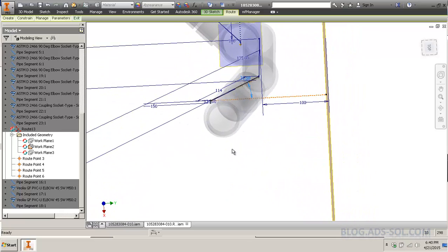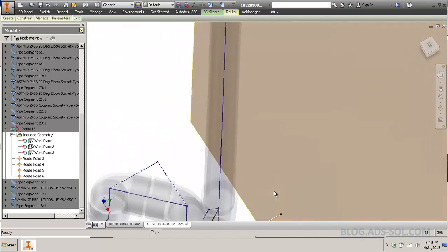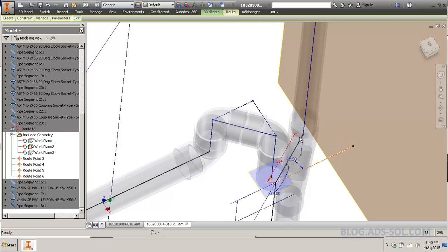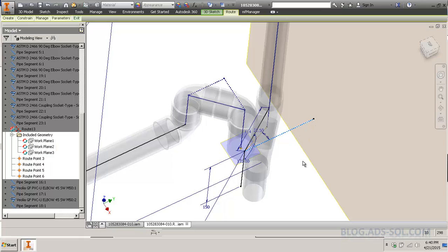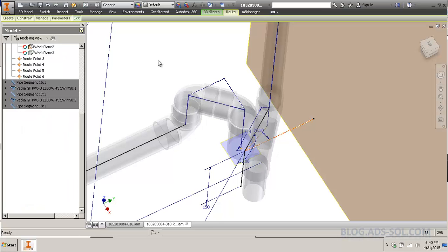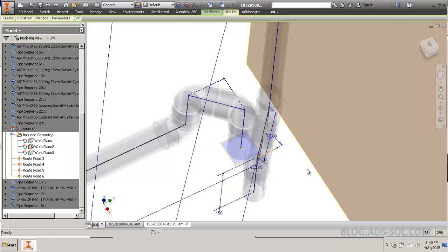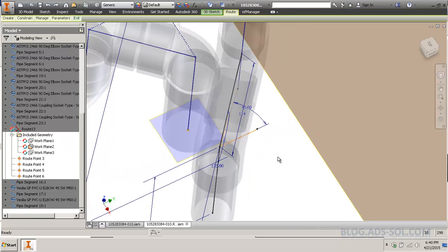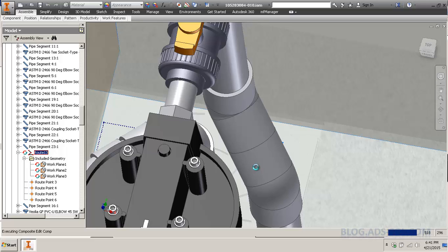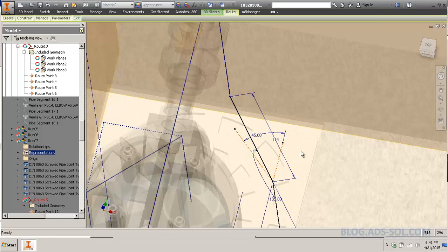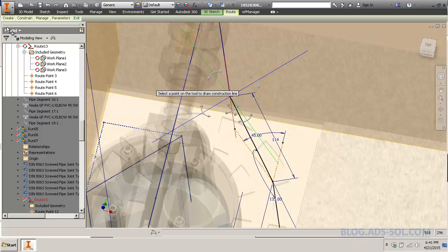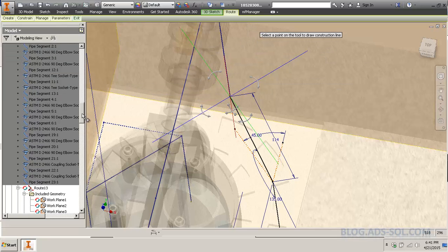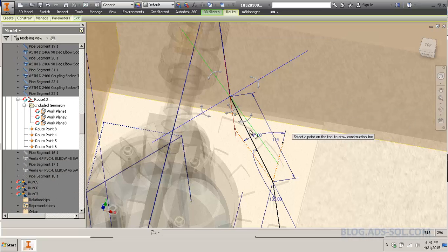But you can actually have weird angles this way. And that's one way to align this. The bad part is that all these lines will be visible inside the assembly. You can always turn the root visibility off, but let me just go back. Where's 13? Come back inside 13. Then from here, construction line. Oh yeah, by the way, construction line only works inside the tube and pipe environment. So if you have it open like I did, it doesn't work.